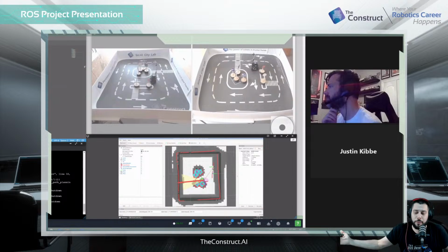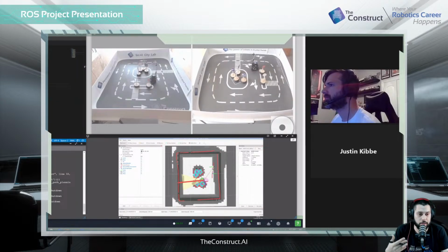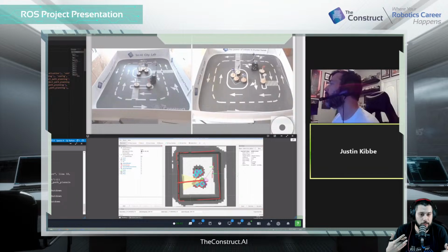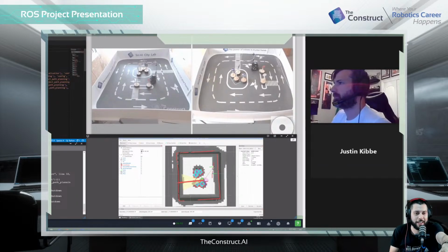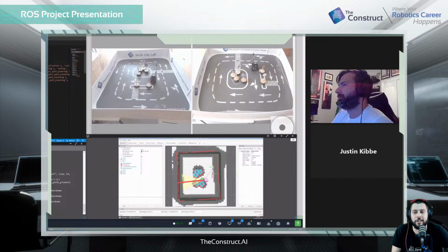So if you were to create a launch file for this executable, you see how they're doing this here, get package share directory. That's basically what you're looking for. So it's an extra thing that finds your path, the equivalent would be like the Python path, and then just puts it there.